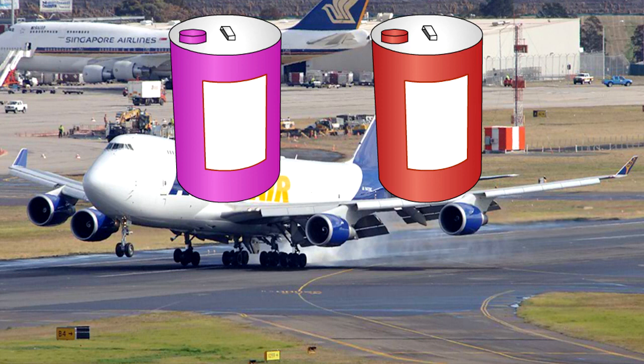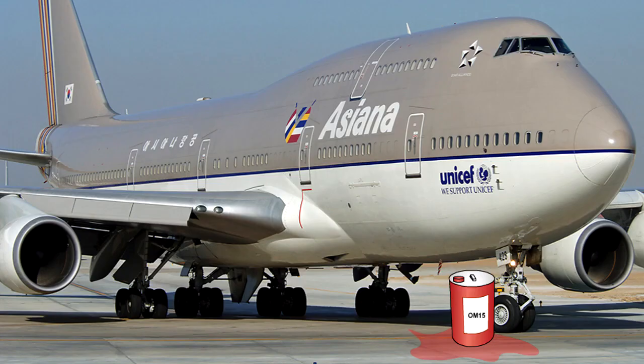It is of major importance that only the specified hydraulic fluid, or its approved alternative, is used in a hydraulic system. If the incorrect fluid is added to a system, breakdown of the seals is likely, causing fluid leakage, both internally within components and externally from the actuators.